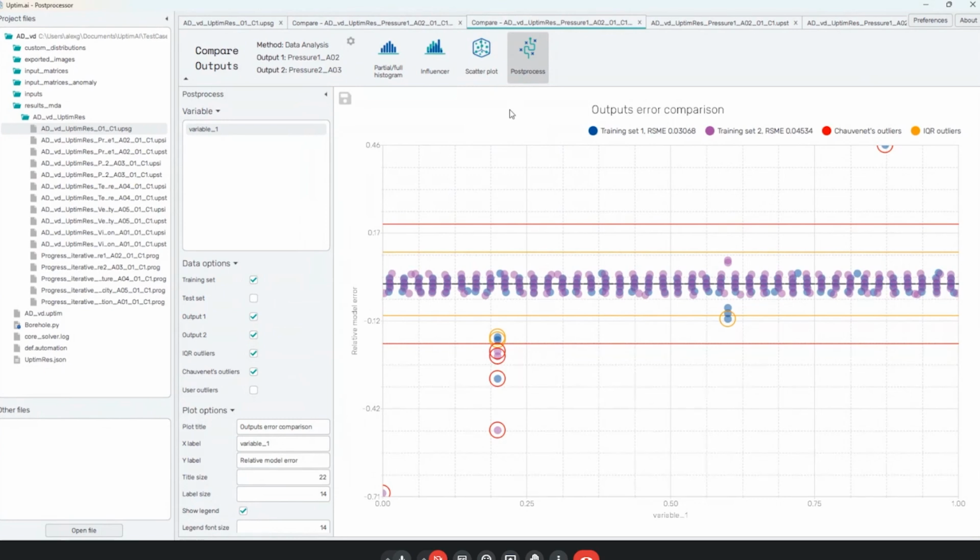In this case, there are 4 positions where we have an anomalous behavior. 3 of them are happening on both pressures at the same time, which can be, for example, an error of the preparation of the experiment, or that it hasn't achieved yet a steady condition, while the last one, the error is only happening on one sensor, showing that it may have been a possible overcharge or something wrong, specifically with that sensor, which should be investigated further.